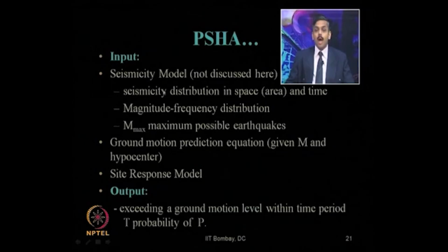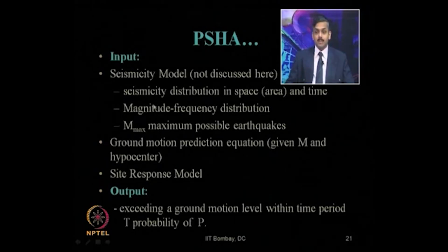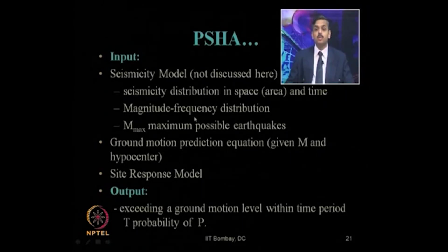Now, magnitude and frequency distribution. Magnitude means, among this seismicity distribution, the values of the seismic events, and frequency means the number of occurrences. Say from a source we get various magnitudes of earthquake, such as 4, 4.5, 5, there are several of these, but there are hardly any of magnitude 7 or 7.5, in the higher ranges.